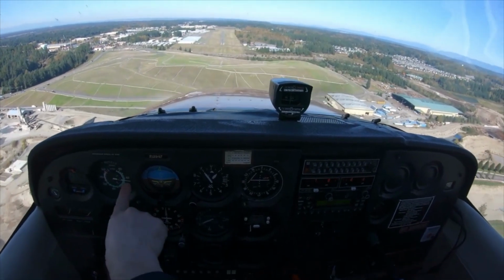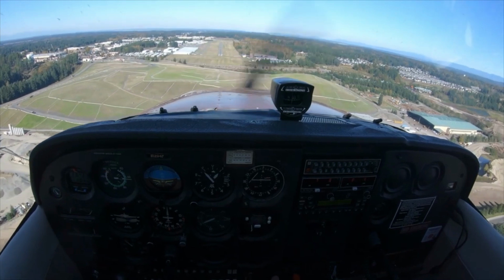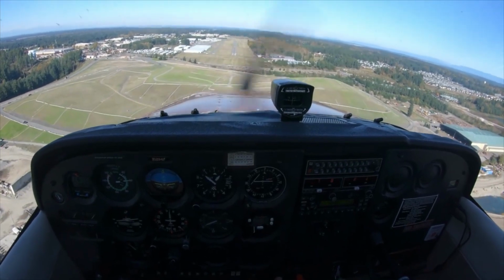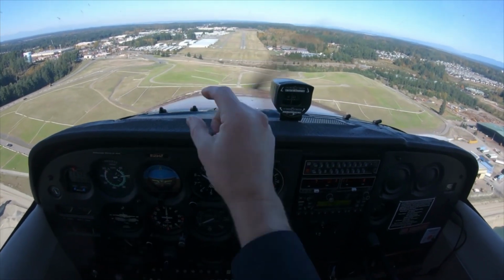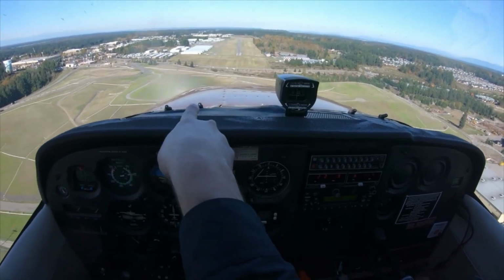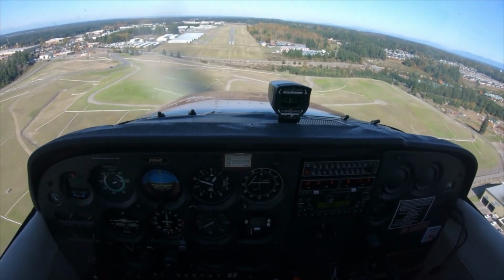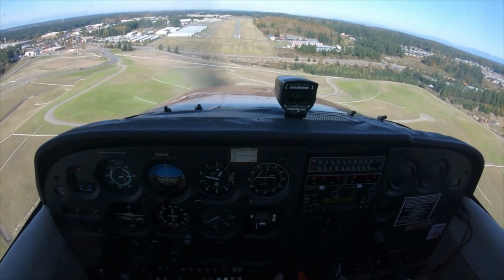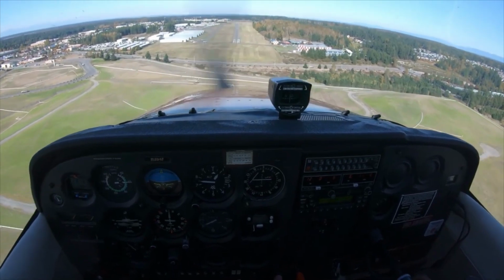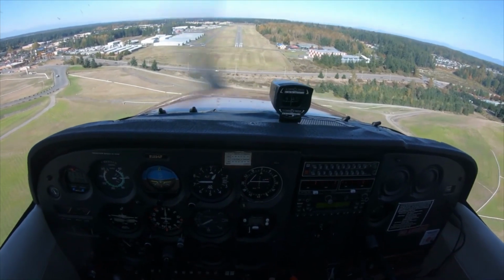Best braking results are always achieved with the wheels in an incipient skid condition. That means a little more brake pressure would lock up the wheels entirely. In an incipient skid, the wheels are turning, but with great reluctance. If the wheels lock, braking effectiveness drops dramatically in a skid and the tires could be damaged.